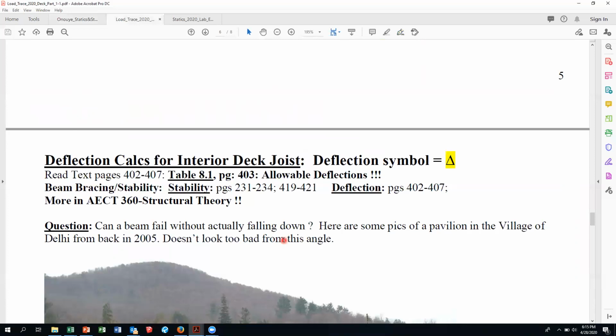But it was failing in deflection. It was also failing in the stresses on the masonry itself because of the lack of a soft joint of the brick coming up underneath the steel angle. So let's look at another example.